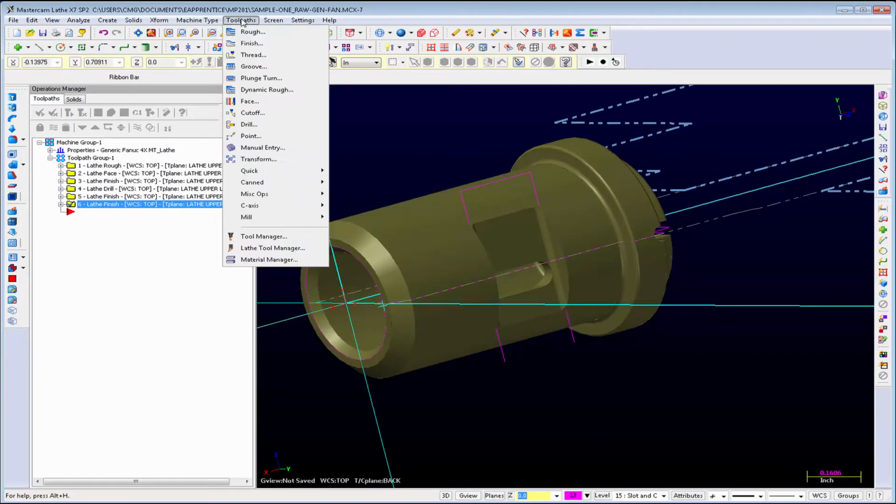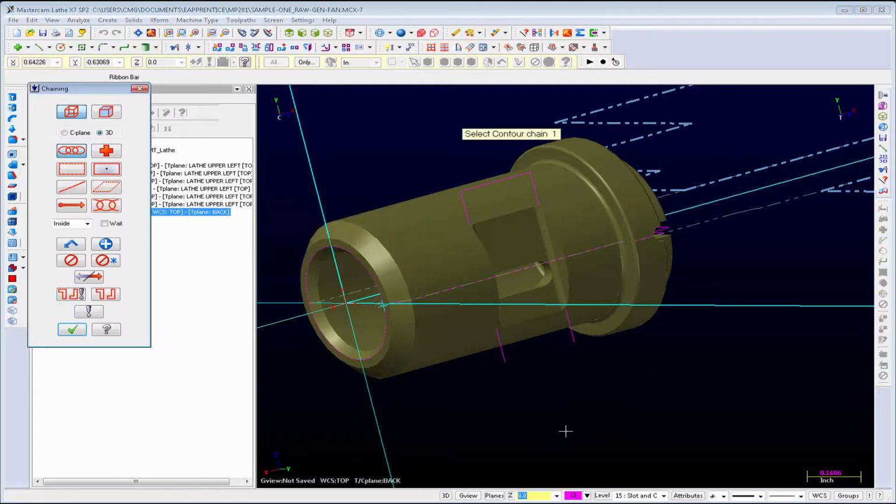So now what we're going to do, tool paths. We'll do the first one here, C-axis. And what we're going to do is a cross contour. Well, actually, so cross contour is generally made like this for making flats on the part. And we'll see if it'll let us do Y-axis machining.